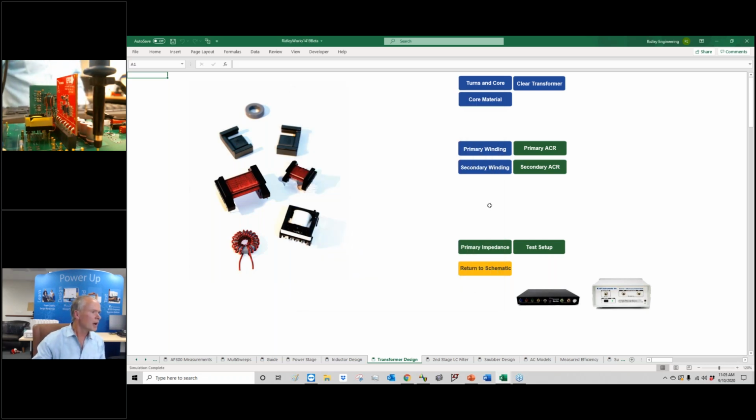Okay. Somebody asked, what about a toroid for lower leakage? You don't normally use a toroid for a transformer, because you've got to get coupling between primaries and secondaries. And as you bend around the corner, you cannot get them that repeatable. I'm not saying it's never done, it's just unusual. It's all about winding placement when you're doing cross coupling between windings. It's not about low leakage, okay? So the toroid just really isn't a good choice for doing flyback transformers in general.